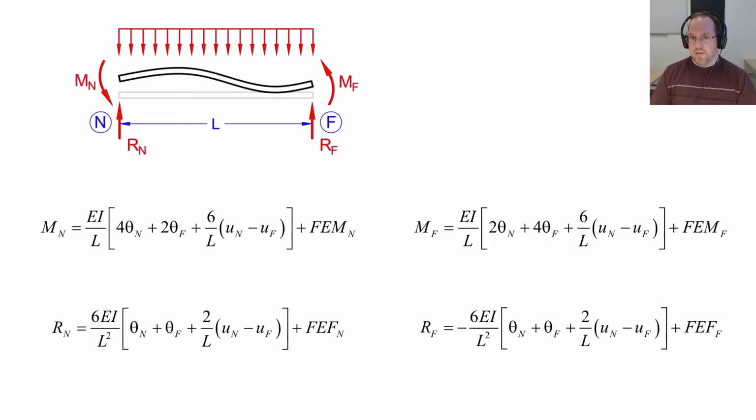Using these equations is going to flip our paradigm in structural analysis on its head in some ways. Previously, we've looked at finding the reactions and shear and moment diagrams directly, particularly for determinate systems. With the slope deflection equations, our primary unknowns are going to be the displacements and rotations throughout my beam. So what we'll do is find all the displacements and rotations first, and then use those in the slope deflection equations to find a variety of reaction forces and reaction moments. So let's see how that works in action.